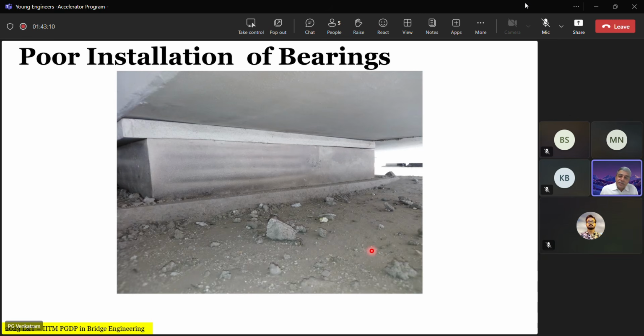And what Sukalyan said, you will look for the load transfer behavior. You can notice that the elastomeric is bulging up to approximately here, correct? And there is no bulge here. Agreed or not? Yes, sir. And if there is no bulging, what does it mean? Now, as a structural engineer, you should talk. That part of the bearing is not loaded. Absolutely. So it's a partially loaded bearing. Then what will happen? This part of the bearing is going to fail soon. It is not meeting the design.